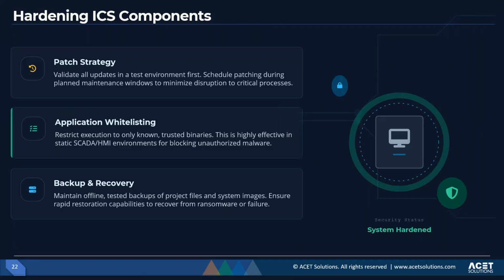Many SCADA servers, HMIs, historians, and engineering workstations run applications that are tightly coupled to vendor-certified OS versions. As a result, patches must be tested in a staging environment and deployed only during controlled maintenance windows to avoid unintended downtime and incompatibility issues.